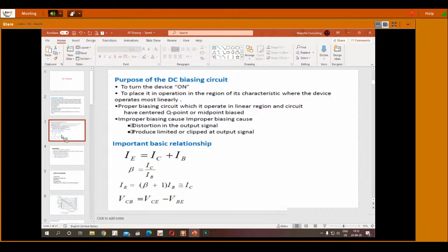Then only will the transistor be in saturation, switched into the on state. But if it is in saturation, it can't amplify your signal. A large amount of current simply flows through, but the voltage levels will not be amplified to the required level based on the current gain.